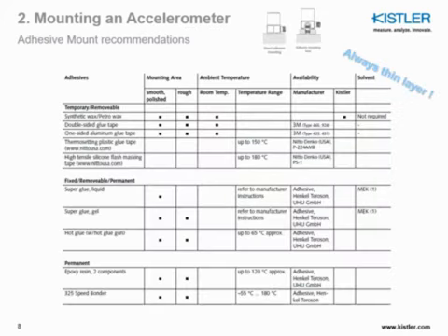Next in line with the most rugged mounting is the adhesive mounting. It can be first a direct adhesive mount using, for example, wax. This is the case if you do calibration of sensors or possibly modal analysis at lower G amplitudes.